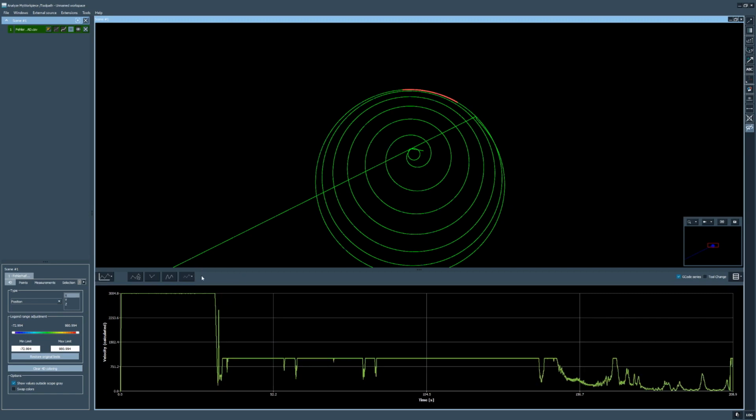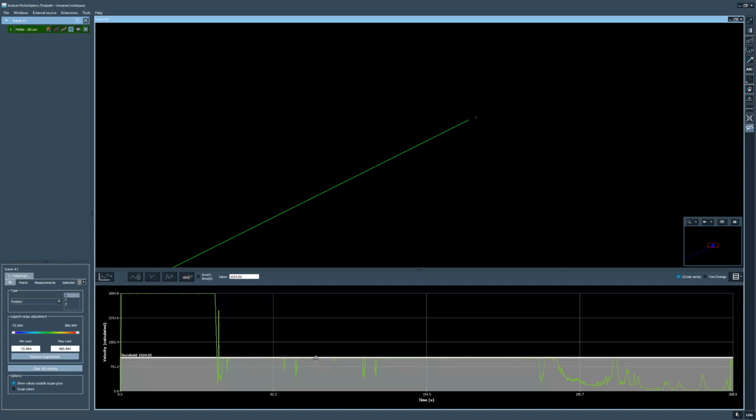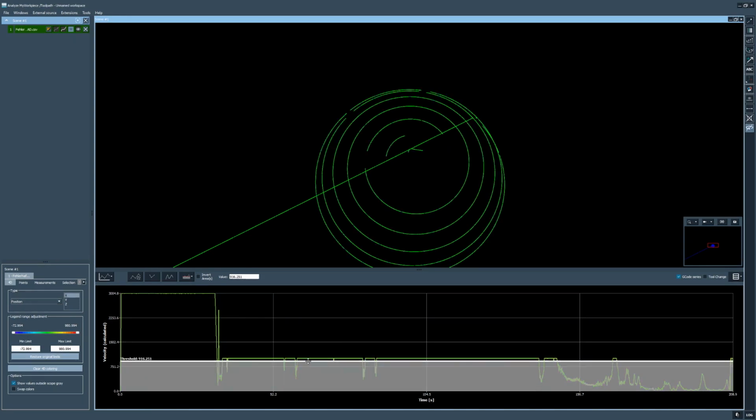With Toolpath, you can visualize multiple threshold types. One is a single threshold type. So you now see a new line, a horizontal line, and this line can be adjusted. Let's say we put a threshold on 950, so that means 950 millimeter per minute for the velocity.